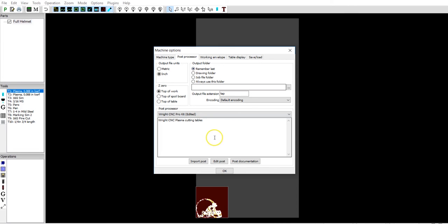Okay, moving on. The final bit here is our post-processor. Our post-processor is going to determine a lot of different rules that are set up within our systems. So this will be where your floating head operation is also going to be included into your code. This is how our machine gets paired with this software. Without this post-processor, our machine, the actual table itself in the Mach 3 system, won't recognize the cut file properly, and you'll likely ruin a good sheet of material by not having the correct post-processor.